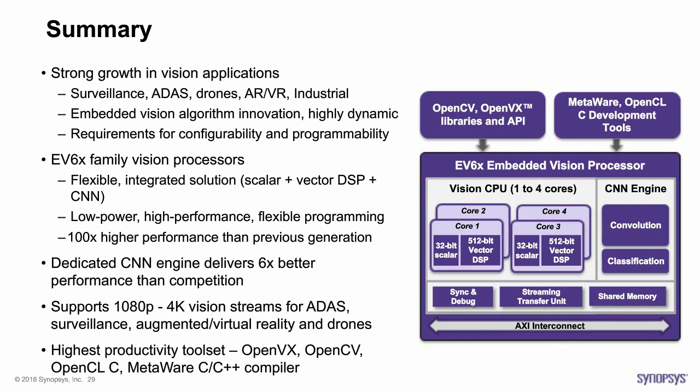Our next one is, what device technology and process are the power numbers from? Well, I don't think we had any in this presentation, but any power numbers that we put out today are typically done in a 28 nanometer process, usually HPM or HPC plus. But the processor itself, of course, is process independent.